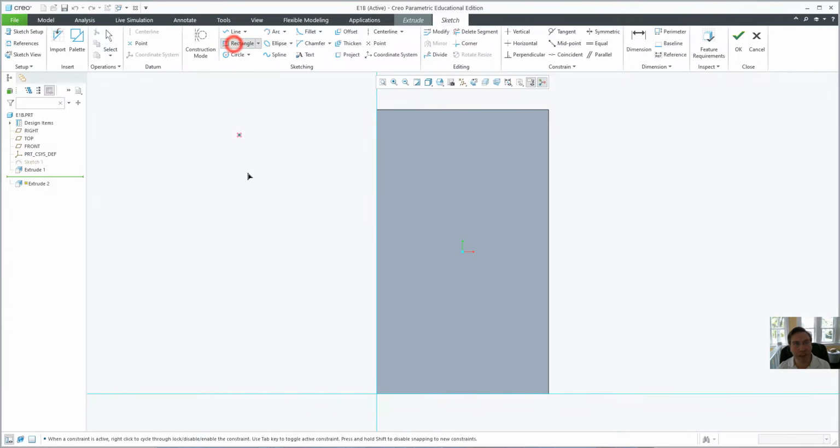Go to rectangle, hover your pointer to the lower left corner of the block. When you get the little symbol like I have here, click and move your pointer to the right and let it snap to this edge. Now notice there's a midpoint snap. We don't want that, not yet, but remember that, because on your lab 2, that really helps you save some time. Okay, but we want it down here somewhere. So just go ahead and click on that edge.